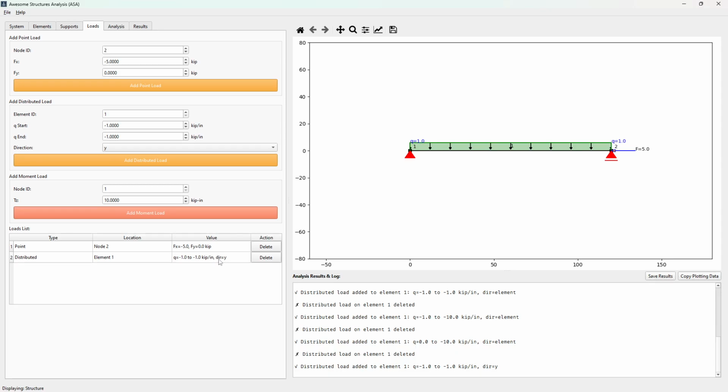As you can see, you can change values here if you want on the table, but you can't use things that don't exist. Like we have an elements 1, we don't have other elements, but for point load we have two nodes, so be careful about changing these ones. Software doesn't look at these ones, it looks at the table. So this is just your inputs. Think of it just like a scratch pad. This is your loads. When you apply them, you add them to the structure.